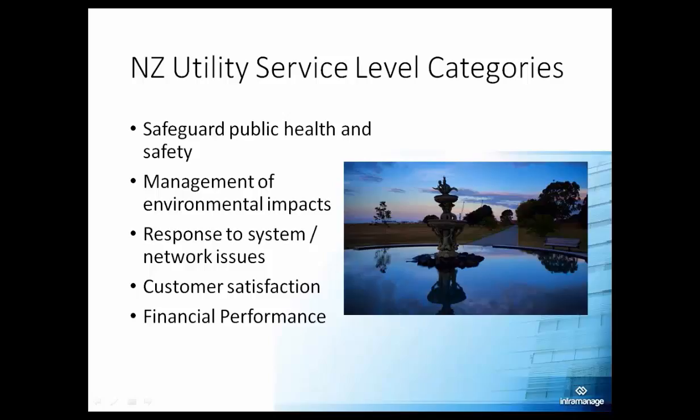So looking at where you need some additional expertise, maybe another good example of where some help might be beneficial is replacement costs. It's often hard for a small utility to know replacement costs of everything, pumps, tanks, pipes, whatever. So hiring somebody who can fill in that data, and say, well, we think a mile of pipe in your system would cost, whatever, $600,000. So they could help you with those replacement costs, because that's something that would be more difficult for your staff to know. Or maybe they can help you think through useful life estimates of how long this kind of thing will usually last.